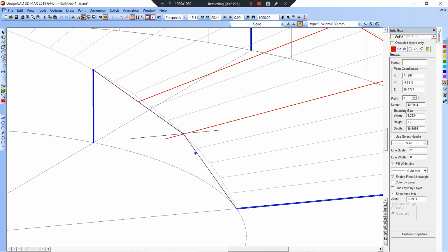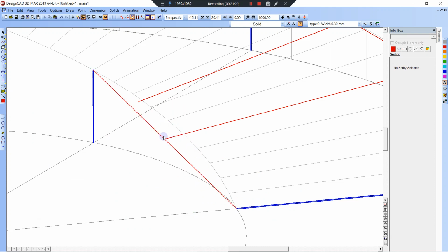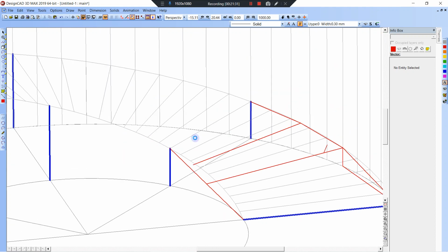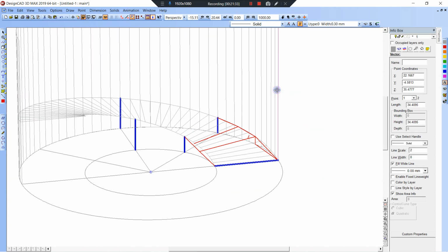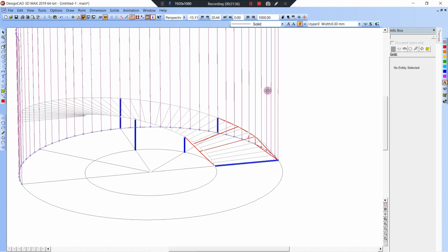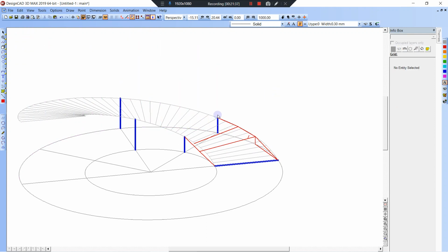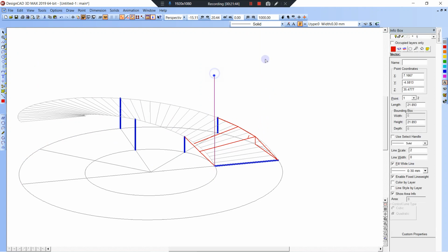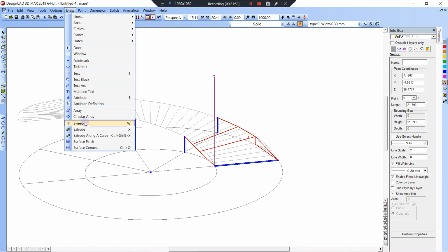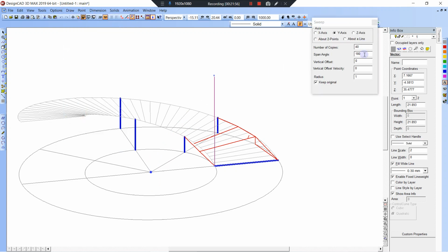On the inside, how you would do it would be Control. Let's do this back to there, right? So you can't run a line through that. Let's say this had a wall on it. Let's get rid of this wall and do a wall here. Enter. Turn it into a gray line. Control H, put a handle on it, enter. Draw, sweep, 40, 180, 0.